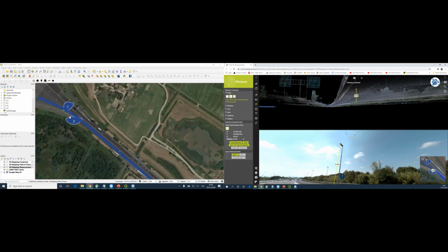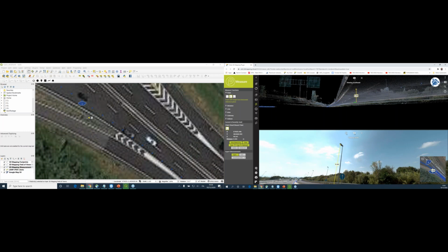Now, if I zoom in on QGIS, you see this yellow dot. Actually, this is the point I am creating through the plugin. This point at the moment is not stored yet in my layer. To save this into my layer, I select my layer, and then I click on this tool here, which is add the measurement to the active layer. So I am doing this. Now this point belongs to my layer.